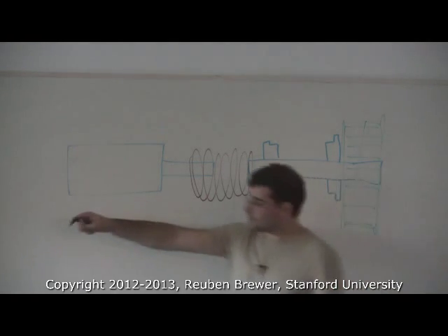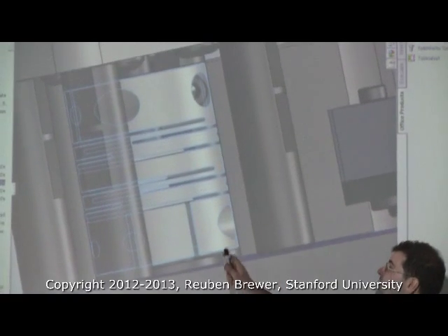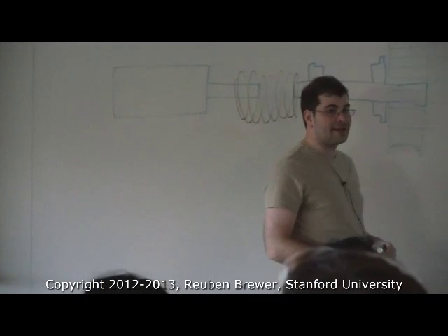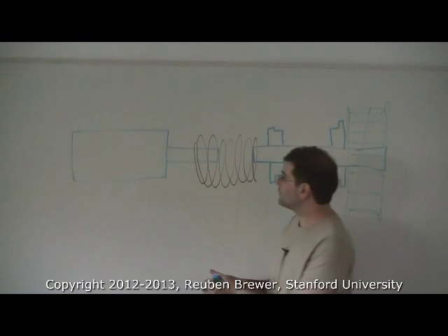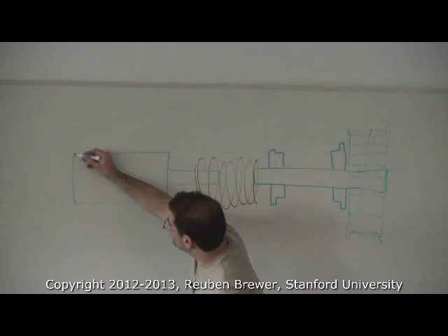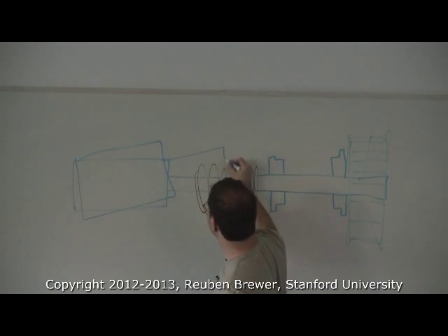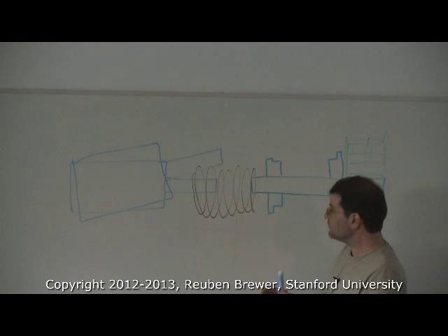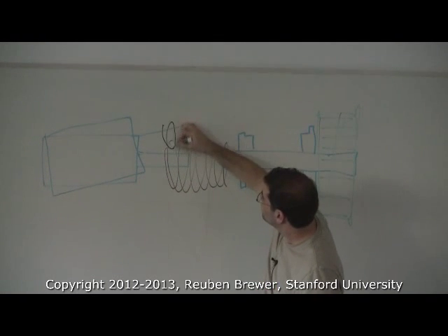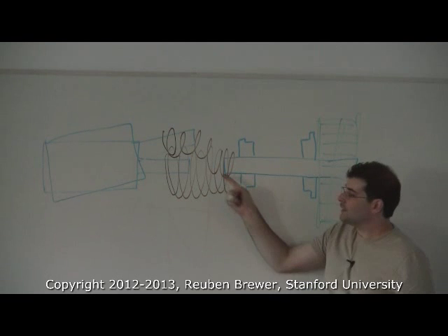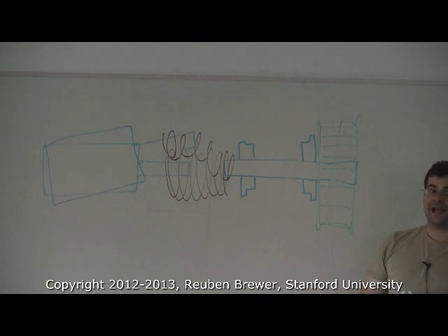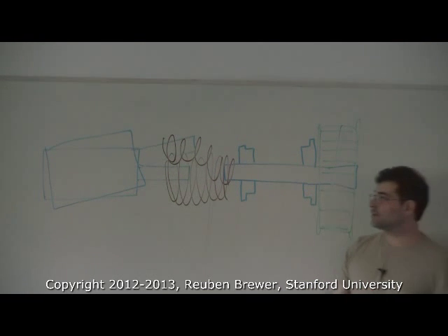So look up at this. You can see these slits are able to bend back and forth like this, but torsionally it's very stiff. So it transmits the torque, but allows what? It allows misalignment. So say we take our motor, and actually it's like this. This is kind of cartooned. I could take the same motor and I can withstand axial offset and also angular misalignment.